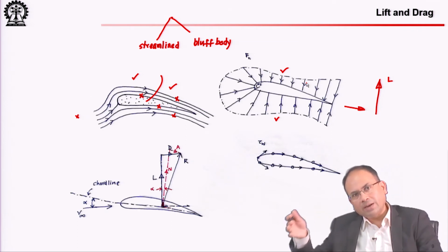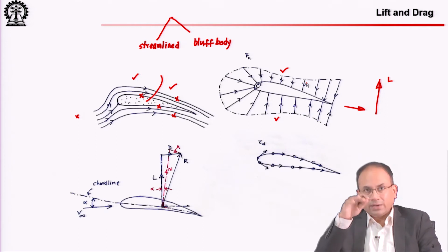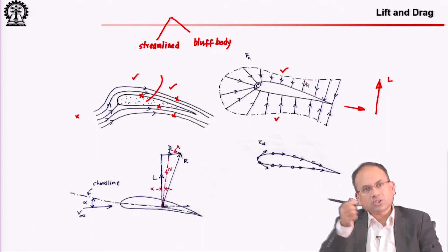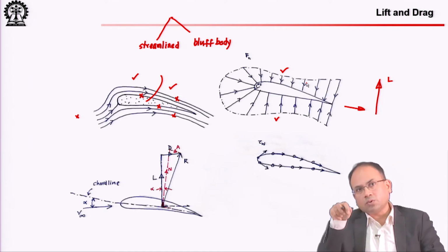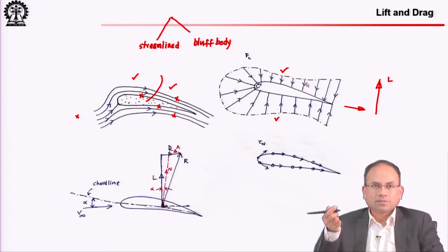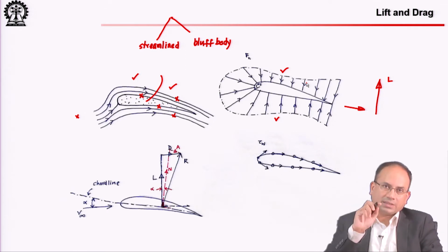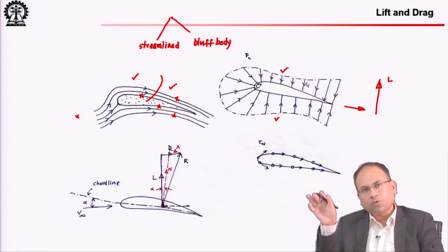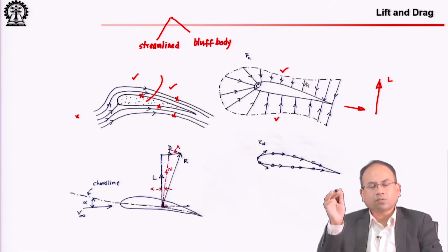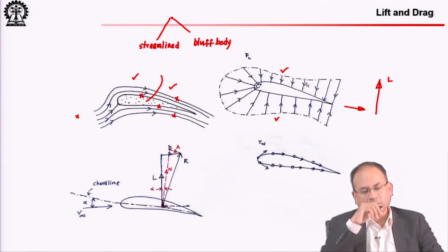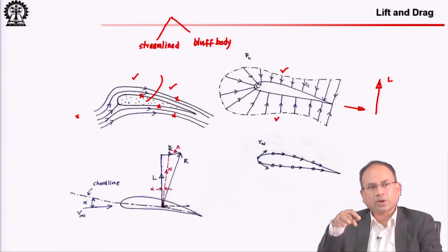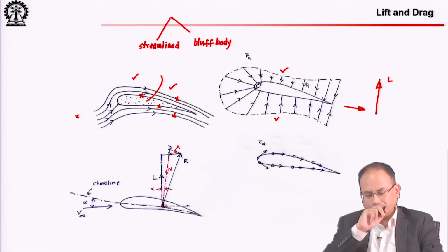The flow will bend around the object in such a way that if you integrate the normal forces in the direction of the relative wind, you will see that the drag becomes 0. So, if there is circulation, you still get some lift, but there is no drag from the inviscid irrotational analysis. And when we do our lift force discussions, you will see that we will spend a lot of time mathematically formulating, using velocity potentials and stream functions, the approach that D'Alembert and mathematicians of his time were taking in analyzing fluid flow.